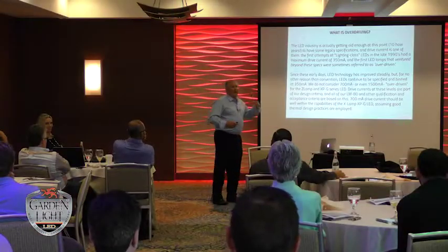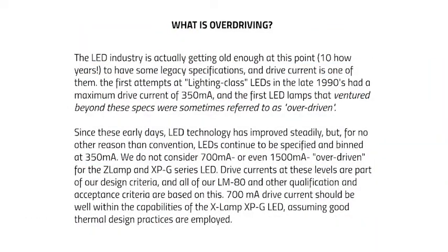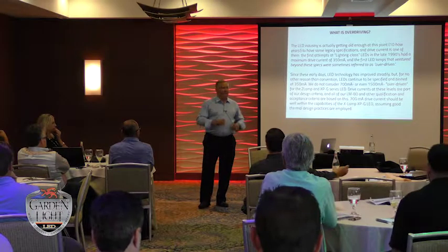Where that gets to is that you can overdrive an LED, and one of the things that I ran into years ago was Cree came out with an LED fixture, and you mentioned Cree earlier. They were claiming that they could drive the LED fixture, and they were driving it at 750 milliamps, and they were failing everywhere. So they came out and said, well, that's overdriving the LED. We've decided we're going to drive our LEDs at 350 or 525 milliamps. And it took me 2 years to convince people that the drive current that you're using is not what creates that life cycle. The temperature the LED's operating at does. Their problem wasn't they were driving it hard. Their problem is they weren't getting rid of the heat.